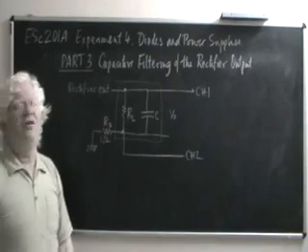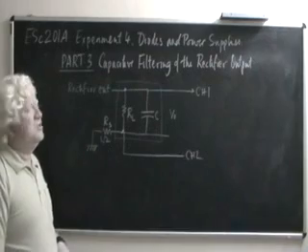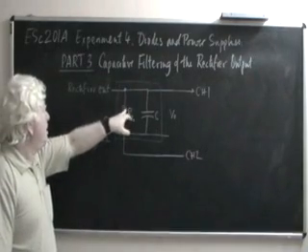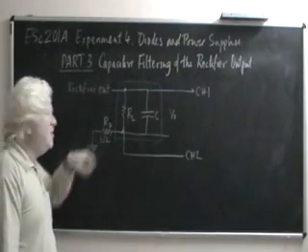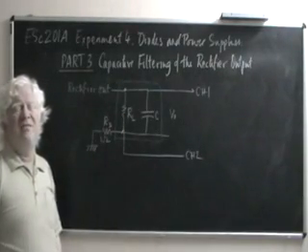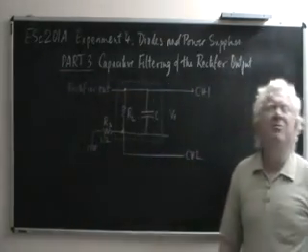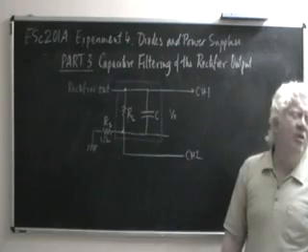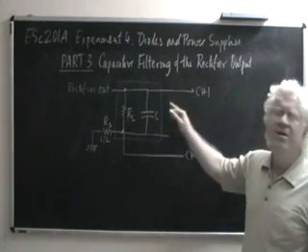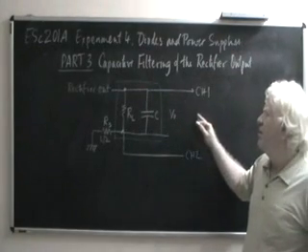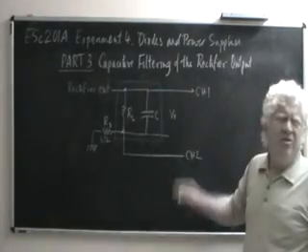We don't need to do it here, because this being a very small resistance, the sum of these voltages would literally be equal to this voltage. Hence, we are going to use the channel 1 output as an approximate measure of the load resistance voltage, or the output voltage of the rectified filtered system, to tell us how it works.